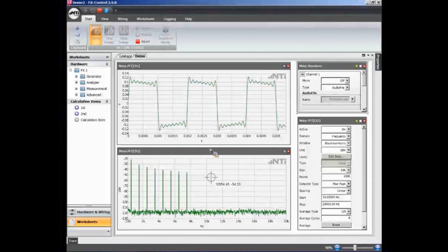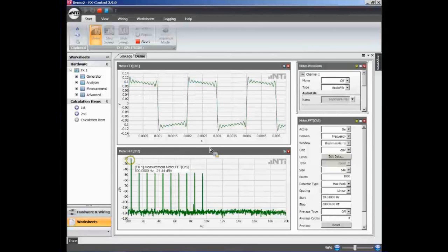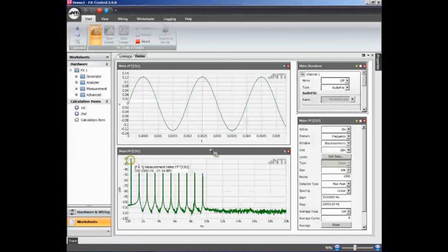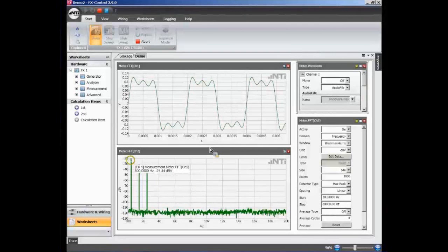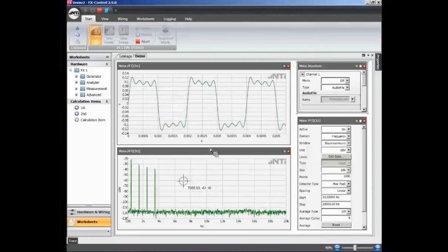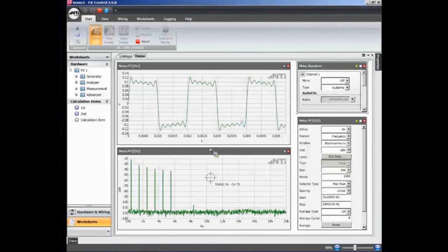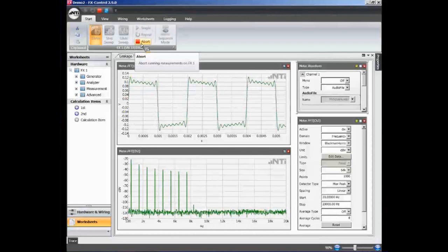The rule that applies to the square wave creation says that you start with the fundamental frequency, we'll see it now again, and then you add 1/3 of the third harmonic, 1/5 of the fifth harmonic, and so on and so forth, and that gives us altogether this nice square wave in the end. So here you see a typical application where you could analyze the fingerprint, the characteristic of a signal that you are analyzing.